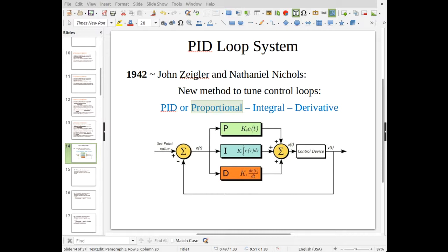the value of delta t depends on basically two things. Number one, how fast does your system change? Like if you're running a heater and you're trying to heat up this very large object, it's going to take a while. So a half a second delta t might be perfectly fine, even a full second delta t, because it may take an hour to heat this thing up. All right, and so if it's a really slow system, it's not that big of a deal to have kind of a slow delta t.